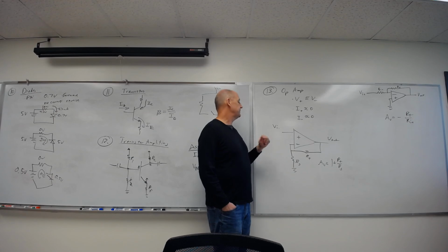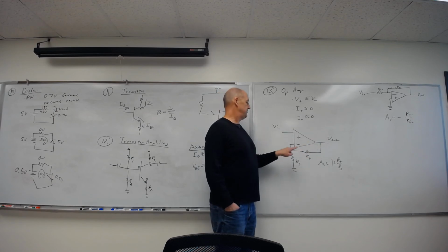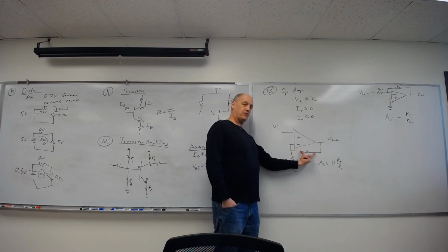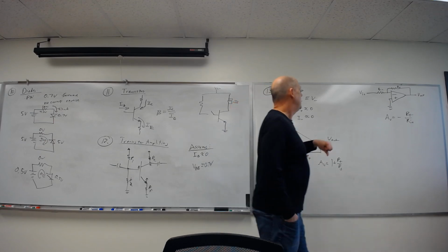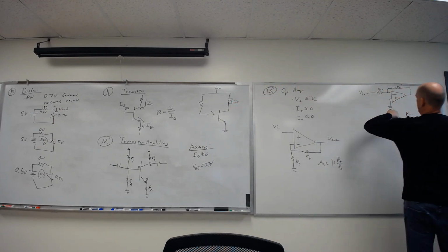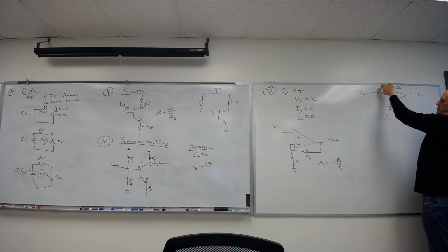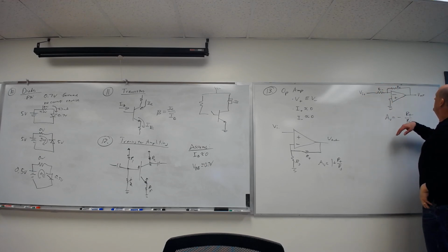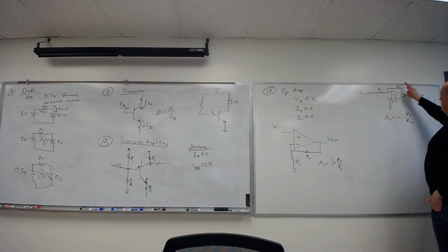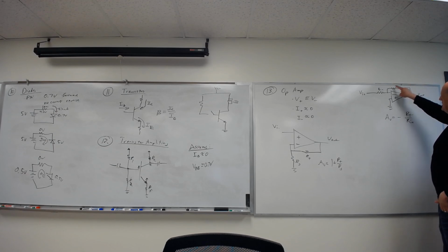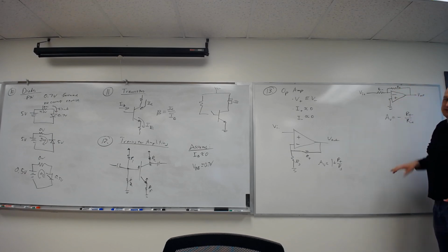Over here, out minus in gives the voltage across that resistor, divided by the resistance. Up here, this is tied to ground, so it's 0. Therefore, that is 0 because they're both identical. Input minus 0 over this, so it's just going to take input voltage over that, which will give you the current. And then I do 0 minus the output over this, which will give you a negative current because it's flowing back. So it's an inverting op amp.